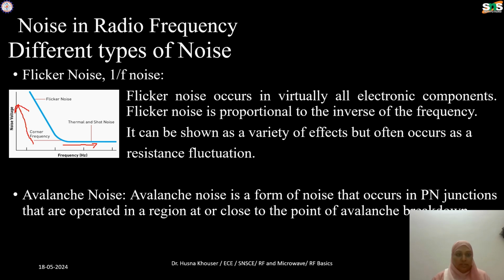And here you can see the breakdown point, the corner frequency, where the flicker noise and shot noise get separated. It doesn't mean that the thermal noise and shot noise do not occur in the low frequency ranges; they occur in the low frequency ranges also. This thermal and shot noise is common in all devices.